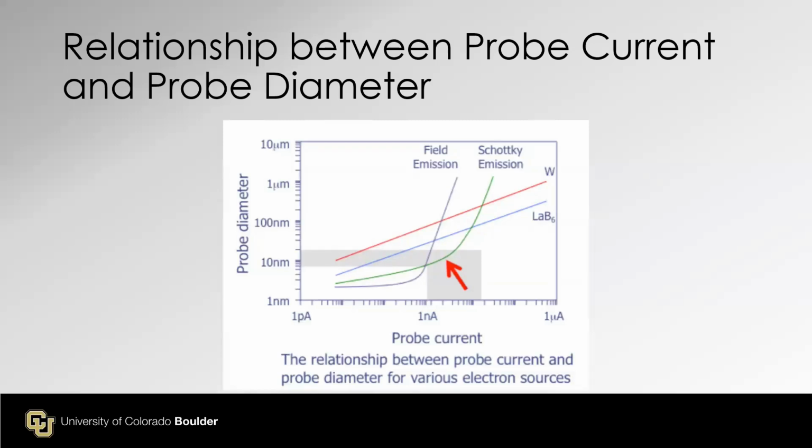two things. Number one is you perform E-beam writing and bring the resist pattern back to the E-beam writer, or the same SEM, to check it. Then you are adding additional dose to the resist pattern.